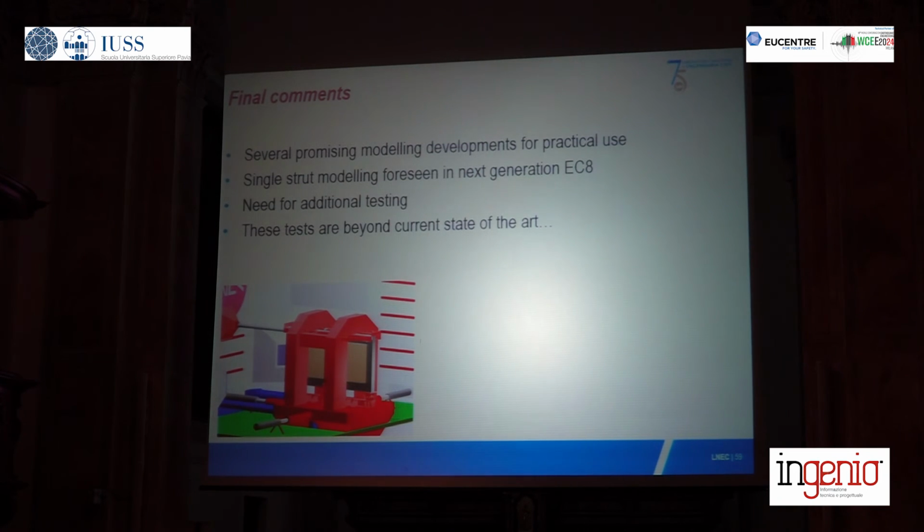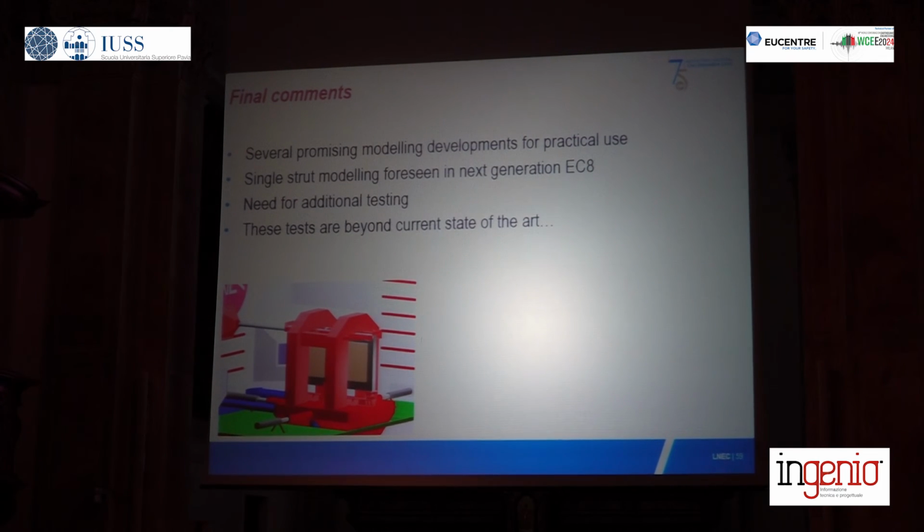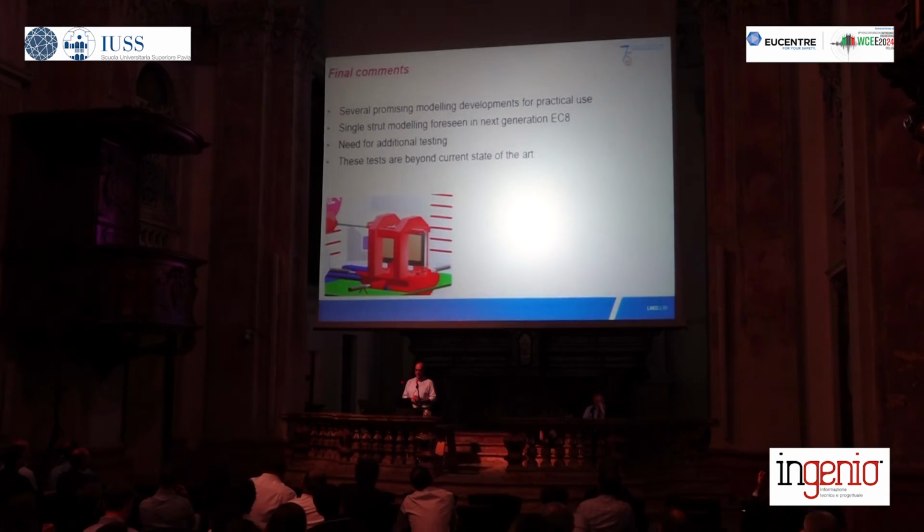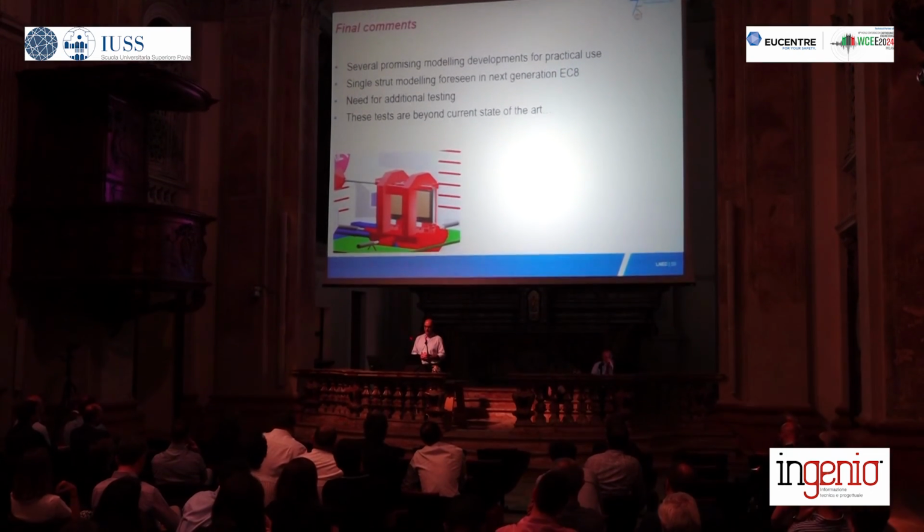So in terms of the final comments, there are several promising modeling developments for practical use that one can adopt. And actually this type of modeling, the single strut modeling, is foreseen for the next generation of Eurocode 8. But for sure we need additional testing. And these tests that I was showing and this test setup, they are beyond the current state of the art in terms of experimental testing.